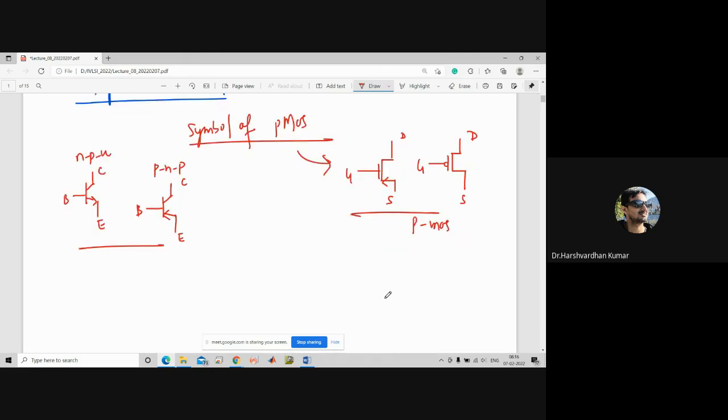This is the reason I always suggest you all, please revise the last lecture so that you will not face any difficulty. In lecture one you took source at the top and drain at the bottom. Source and drain, in case of MOS transistors, I told you both are symmetrical, if you remember my sentence. So this is the symbol of NMOS.